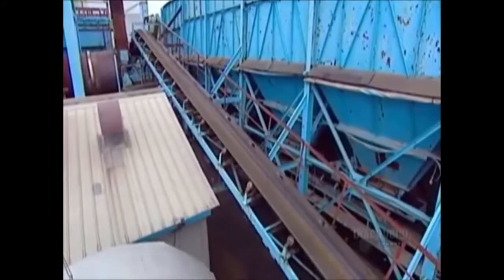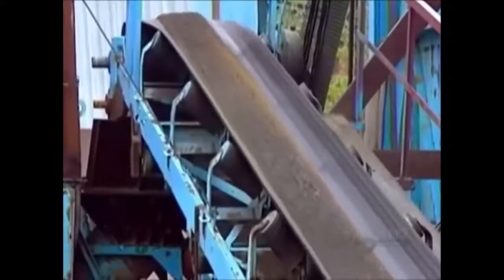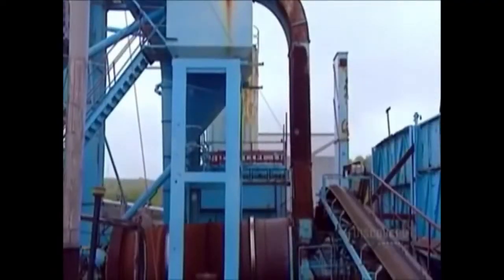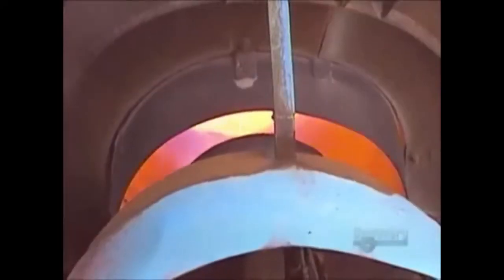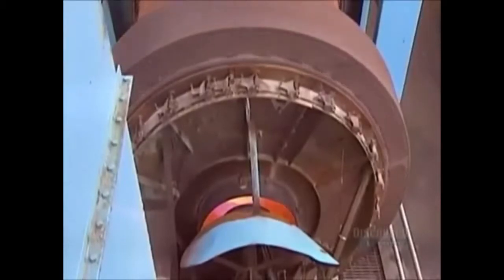The drying process, which takes about a minute, removes all traces of humidity. This will enable the materials to bond better with the asphalt cement. Screening equipment then re-separates the dried ingredients, making it possible to precisely weigh out the required amount of each one. Everything then goes into a mixer. As this demonstration shows, the mixer blends everything thoroughly.